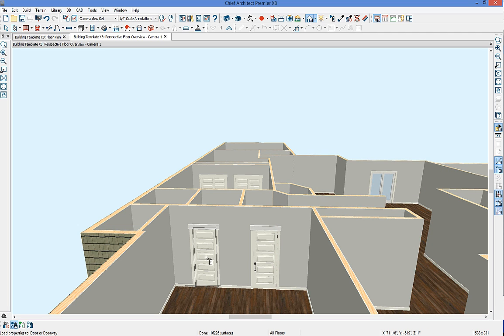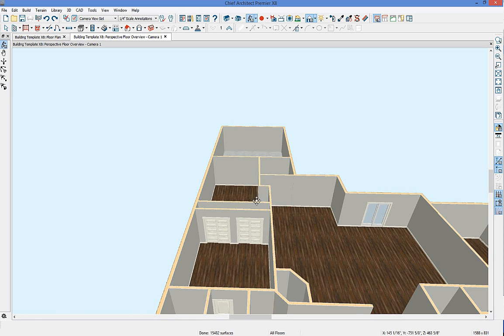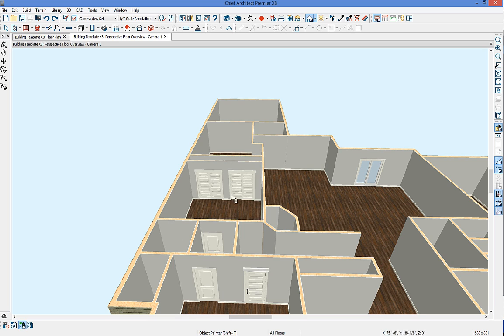So with one click, it's updated that single pocket door in my plan. And notice I also had options to narrow or expand the scope. I could have pasted onto the entire floor or onto my entire plan. So if I undo that and change to floor mode, we're going to raise up here so we can see what's going on. Now, when I click, it's going to apply to that type of door throughout my entire floor.